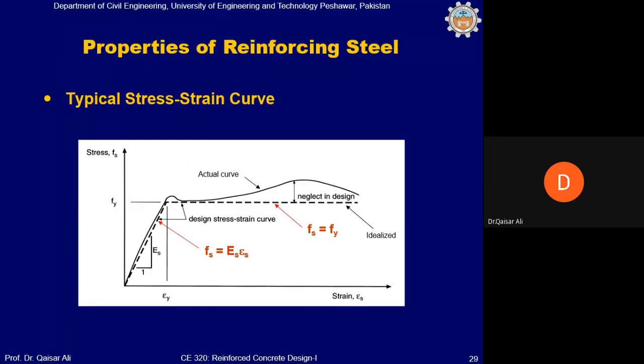this has been determined from the test. But this remaining capacity from 60 to 75 will be kept as the reserve capacity. This will also give us a factor of safety, and this will also ensure that the steel fails in a ductile manner, and the building, when it fails or collapses, will give us a degree of warning, so we can evacuate the building well in advance.